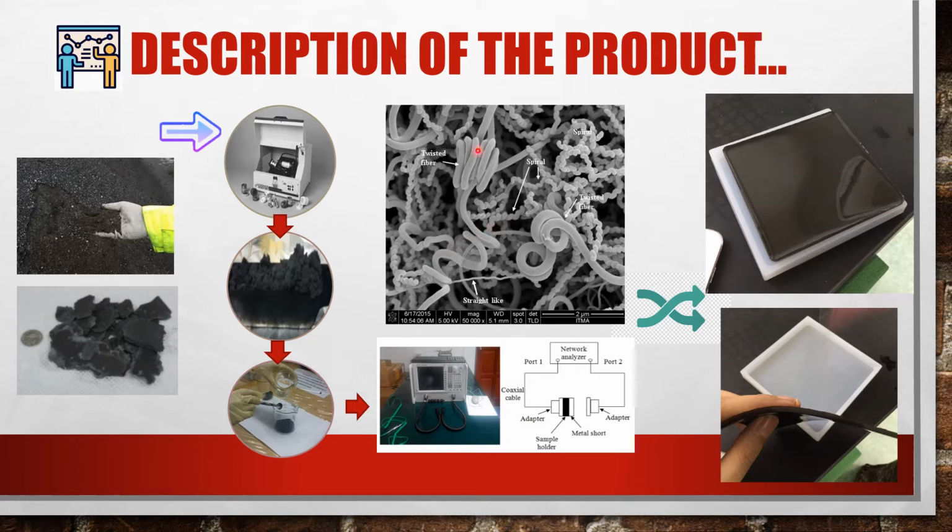Okay, so this is the example of the FESEM or the micrograph of the sample after being synthesized by using chemical vapor deposition, which is to produce the carbon nanotubes. So we can see that there is actually a mixture of twisted fiber, spiral-like, straight-like, and net-like fiber. So all of this actually helps in absorbing the electromagnetic wave, which is we can have multiple reflection of electromagnetic wave in the sample.